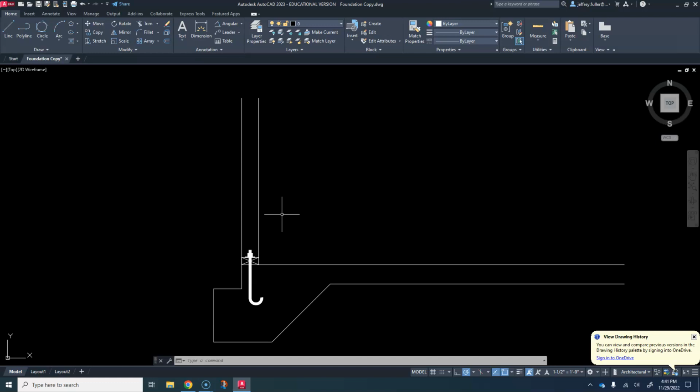And the first part is going to be the interior of the wall, which is on this side where I'm circling my cursor. That is the inside of the house. So I'm going to do an offset for my drywall. Drywall is that chalky substance that is on the inside of your house, on all the walls. It's what you push tacks into to hang up a poster or what have you. I'm going to offset this line a half of an inch, because that is the typical thickness of drywall that we use on most any application. So using the offset tool, I'm going to offset 1/2 inch.